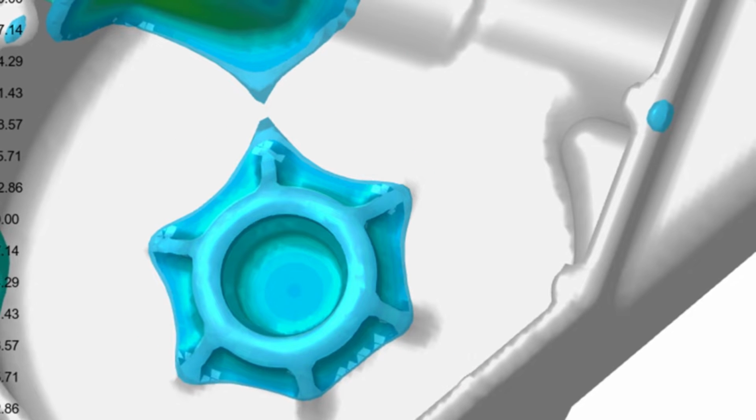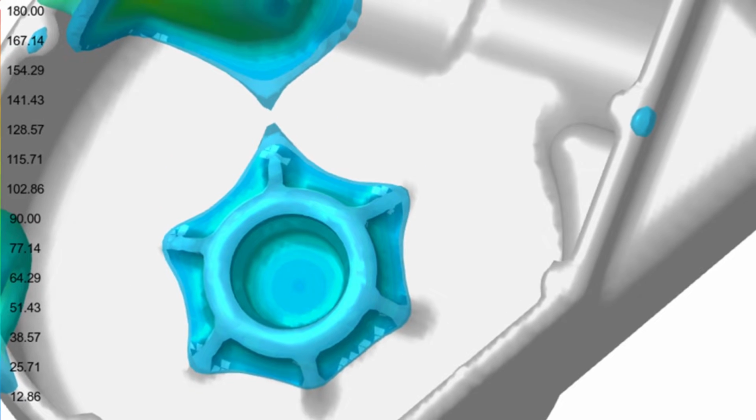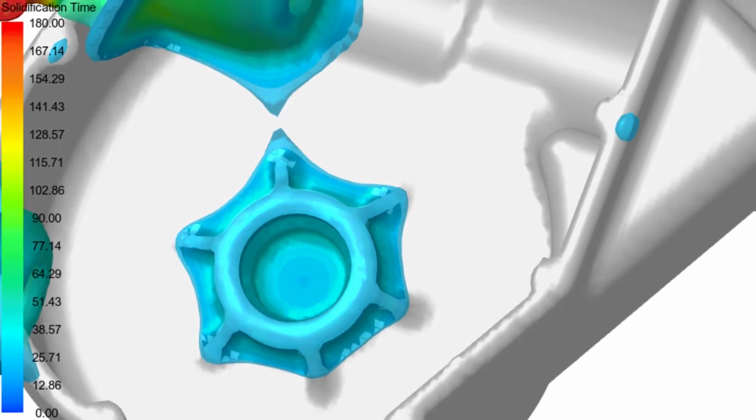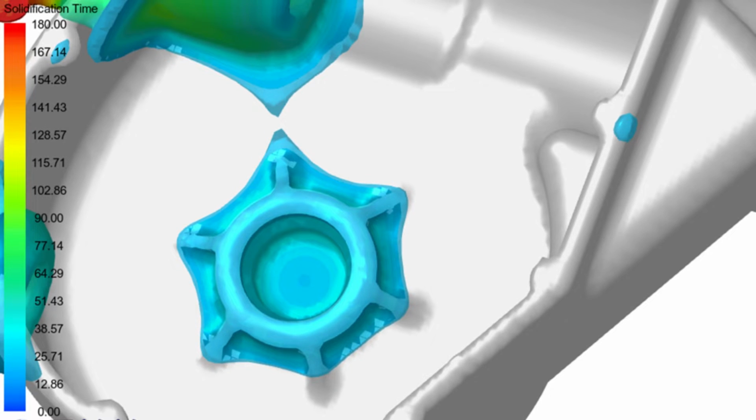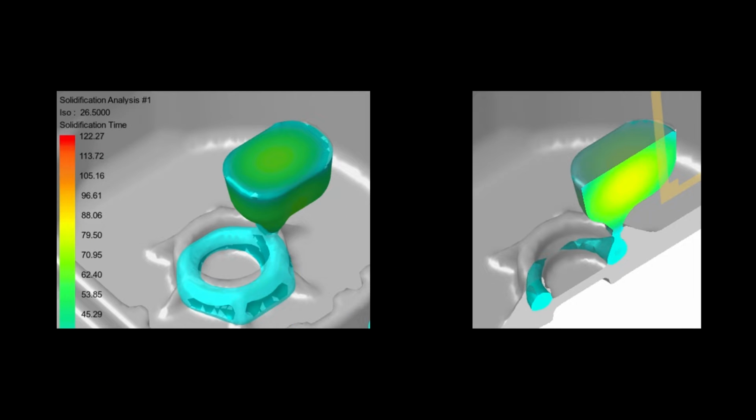Two possible solutions would be to either provide additional cooling to that specific area, to make sure it solidifies before the surrounding metal, or to feed that area with a riser that stays molten long enough to provide the extra metal needed as the feature solidifies. We decided that the addition of a riser in the sand core would provide the most robust solution, although cooling was also an option. Here, the pictures from our simulation show that the added riser remains liquid, and continues to feed the casting in the area that is last to solidify, thus avoiding a shrink defect and solving the problem.